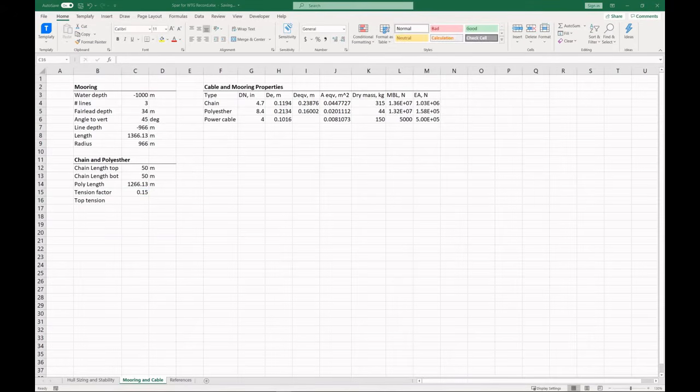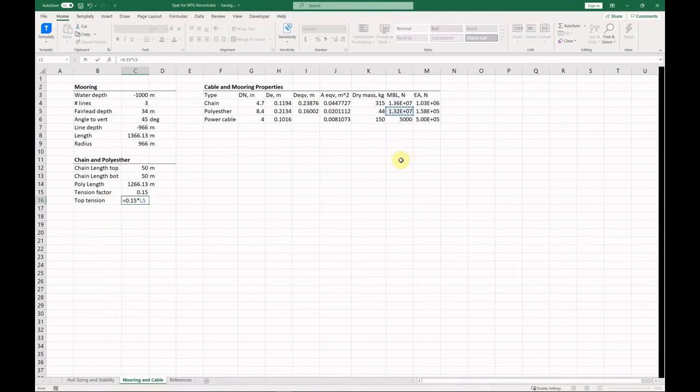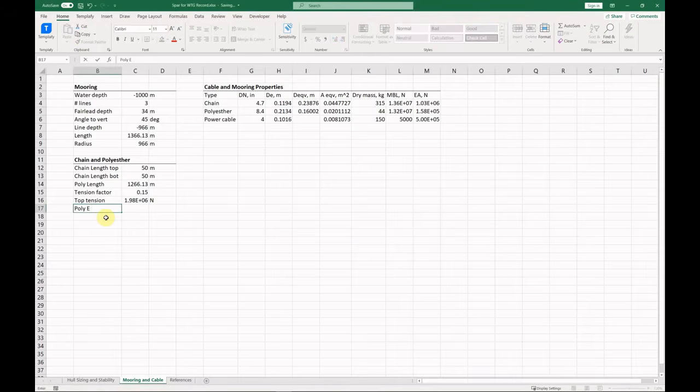Now, the amount of axial deformation of the polyline can be estimated. To target the top tension in the Ansys model, we need to compensate for the deformed length. As the deformed line will be longer after tension is applied, we deduct the stretched length from the total.